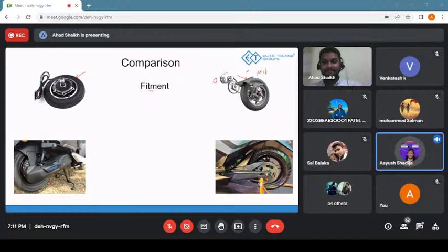Well, the belt-driven actually increases the center of gravity, which might be a disadvantage, but it's actually helpful with space management. And definitely, it's a big advantage in terms of aesthetics as well. You can have a cooler looking two-wheeler with the belt system. Yeah, Ayush, that's correct.